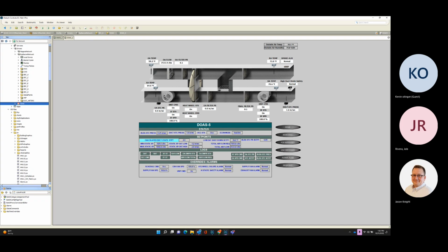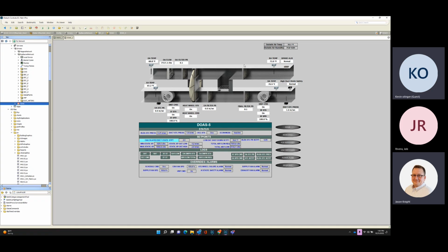Last week, I brought it up to the commissioning team, and I haven't put it on the graphic yet because nobody asked me to. I just took it upon myself to add logic in our Distech controller that's in each one of these units to shut down the DOAS if it goes below 36 degrees. The only thing I have on here is this set point in the middle of the screen, low DAT shutdown set point. I asked Dennis if it would be wise to send the RFI to put a big old thing on the graphic here that says, hey, you are shut down on low discharge air temperature, and make it flash at you guys, because there's no mechanical or electrical interlock safety to shut these down.